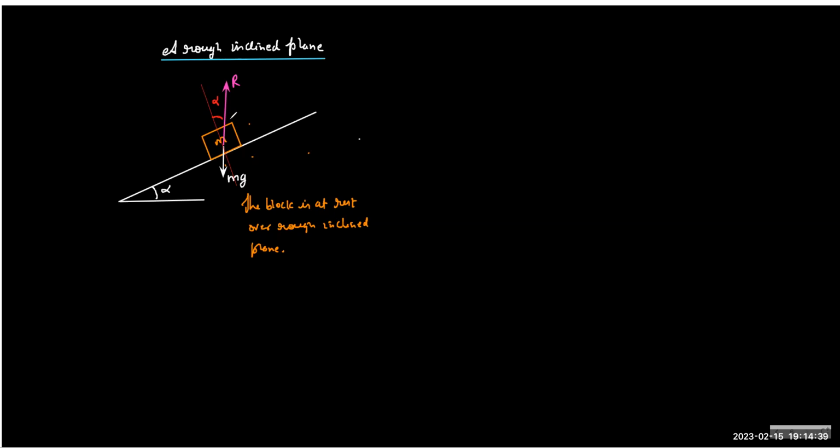And therefore, pretty much you can say a lot of things. Now, if you want to ask what is friction force, what is F? F is which component of R? F is always R sin alpha. Very good. So R is the net force, no? So to find the friction, what will you do? You will resolve R parallel to the plane, right?